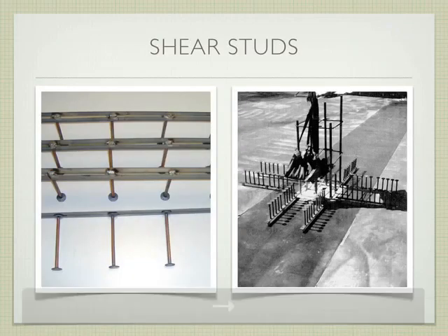The examples in practice, welded to that steel. Here we are with the formwork itself, the columns coming up through. You see the vertical bars of the column right up here. These are the shear studs that are then going to attach to the slab. And those are going to help transfer any kind of weird lateral loads that happen on the building down into the column rather than breaking between the slab and the column, causing it to collapse.